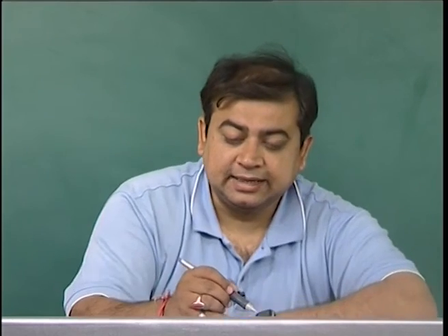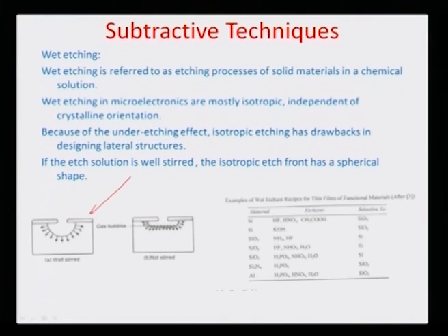So, let us look at isotropic etching. In isotropic etching, as I mentioned before, the etchant is able to remove or erode away material at a uniform or homogeneous rate in all the directions. This, for example, is an illustration where there is an etch protective layer, which is now emboldened by the red highlight here. This window in the etch protective layer gives access to the fluid to go in and start etching away the material underneath this protective layer.